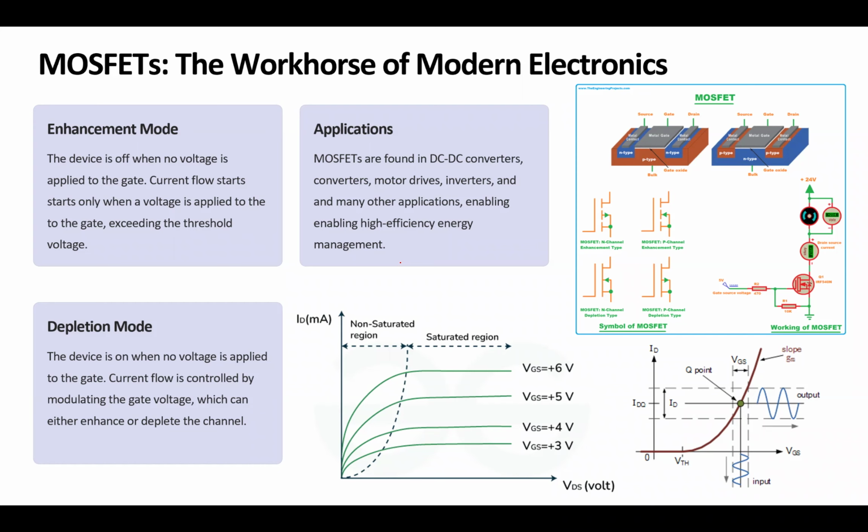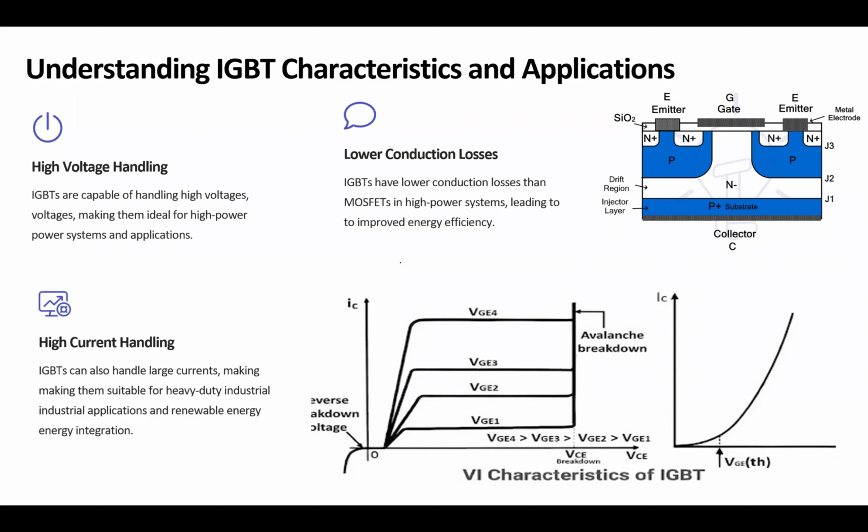Now, IGBT is kind of similar to the MOSFET, but as we said, with different technology. Same as MOSFET, we have a threshold for a voltage of the gate in order to turn on and off. You could see that the characteristics of the current that is drained from the IGBT versus the signal that you get to the voltage is somehow similar to the MOSFET. Same kind of behavior.